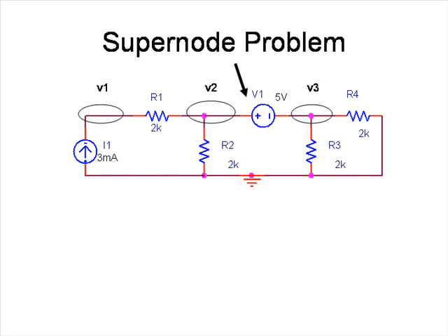However, unlike the previous problem we did in the first video, take a look at this. We have a voltage source. We can't exactly solve this problem currently with what we know with the voltage source that we have here. So what we're going to do is turn the nodes V2 and V3 into supernodes. First we'll take V2 and V3 and we'll bring them together, like so.